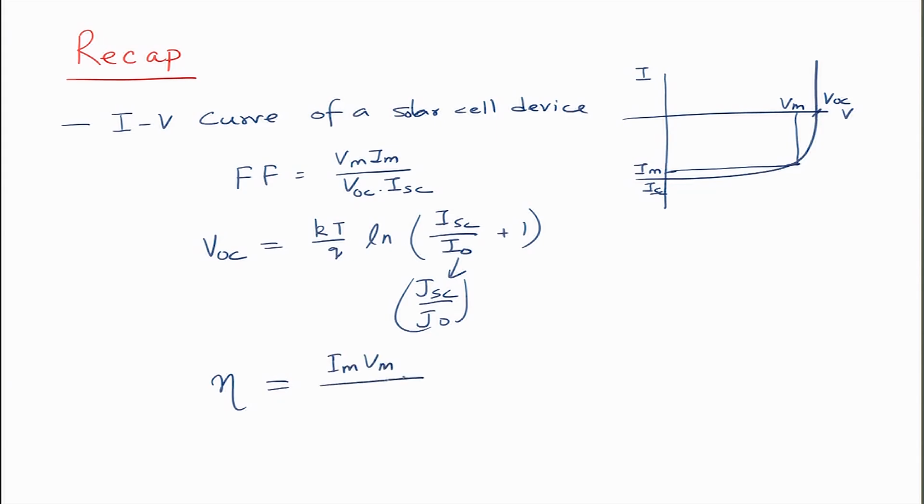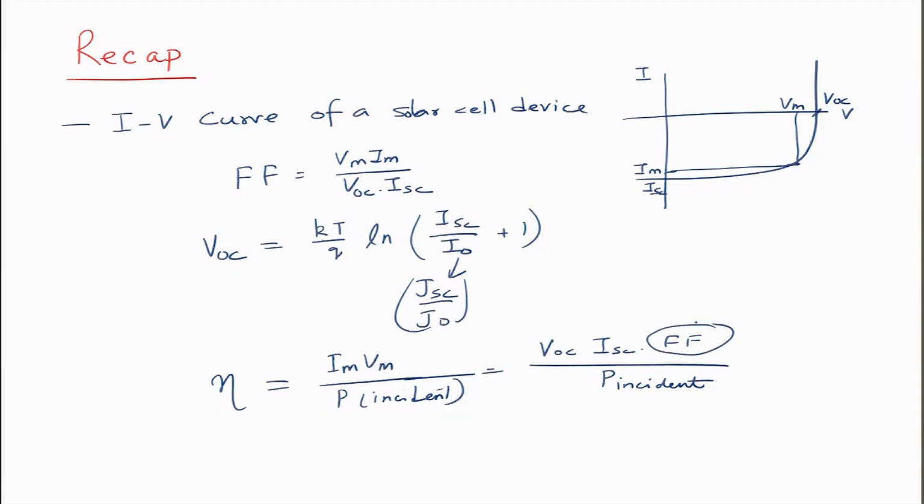divided by incident energy, and this would be equal to VOC ISC into fill factor divided by P incident. So, the idea for a device engineer is to maximize this fill factor.